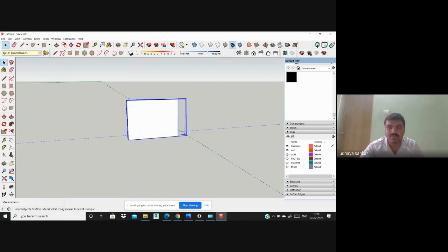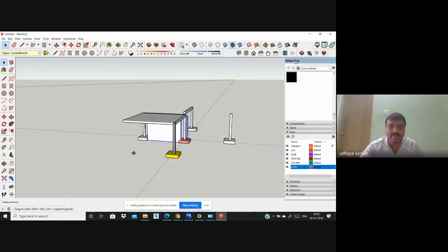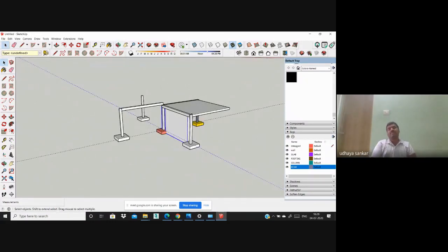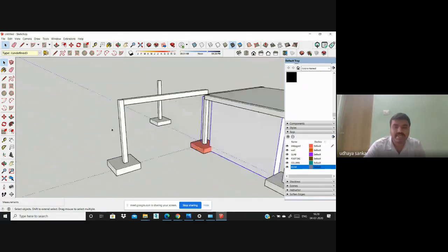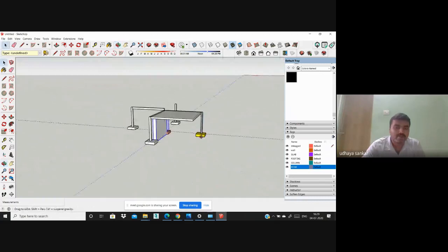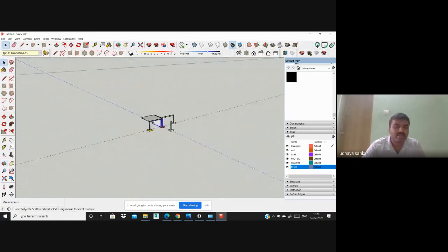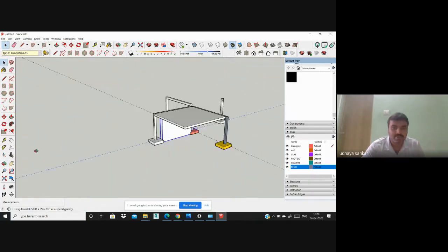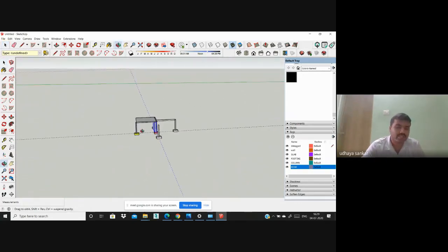Then go to tags, make visible. Now you see the walls and the footings will be calculated automatically. This is the main thing, structural and architecture combined, right? This is the main thing for estimation also. You simply create a tag on any parts, windows, doors, or anything. Flooring also: you create one floor, name it as floor, make a group, and the quantity will be calculated, right? And the others, footing, beam, columns, etc., are also easily calculated. Architecture purpose, right. Do we understand? Beams, columns, slabs, how to create the structural elements and how to calculate for architecture purposes, right?